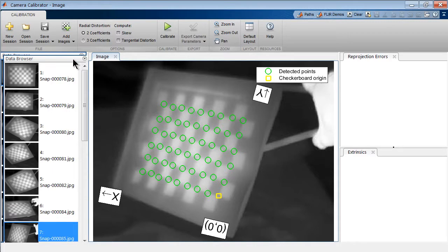And also one thing to keep in mind too is you're going to want to keep it at 1x zoom. You do not want any zoom taking place. You want to be taking it at the actual resolution. In our case it's 320 by 240, because if you do any sort of resizing, it will actually interfere with the algorithm. So let's go ahead and calibrate, and before I do so, you can see we have some parameters.